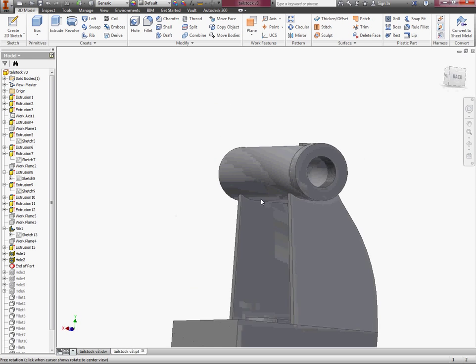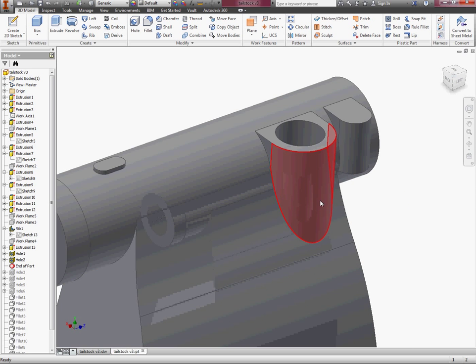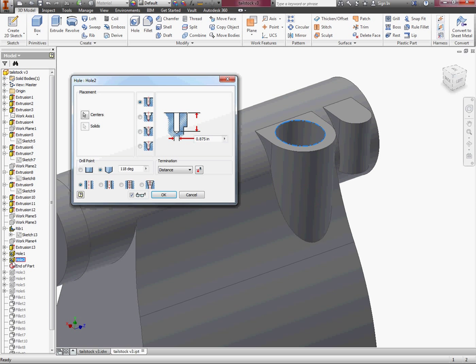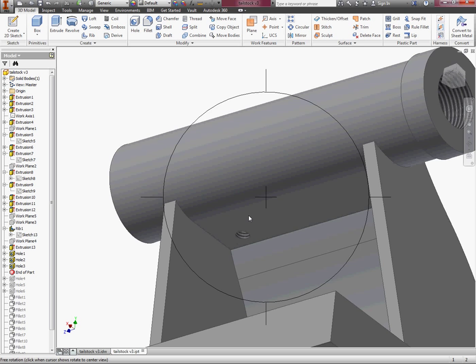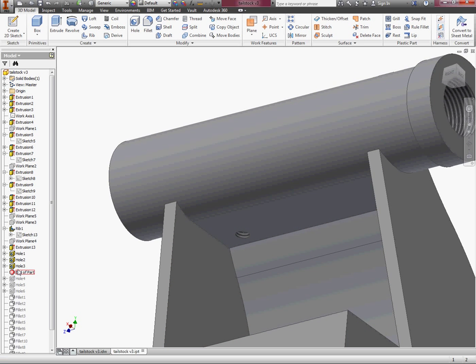Next hole is up on the platform. This is a little bit different. We're actually going to do 2 holes in the same spot. This hole was made by sketching on that surface. New sketch, finish, use the center plate, go down. That hole is a 7/8 diameter hole, goes down 1.25. Then you're going to sketch right here on this surface again, make another sketch, then hit finish, because all we're after is that little yellow dot in the middle. And you're going to make another hole that finishes the rest of the way through in the same spot, because we just need a little area that's threaded.